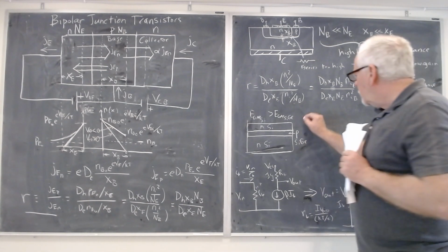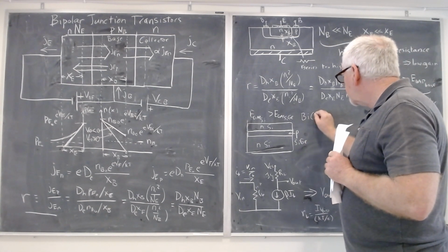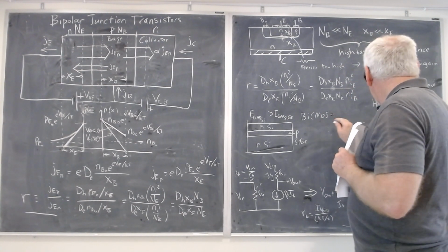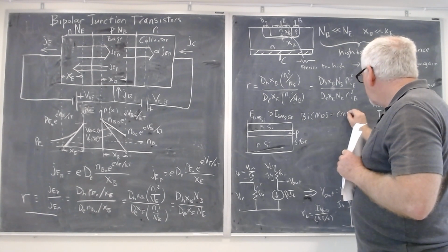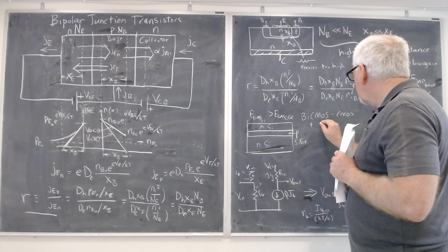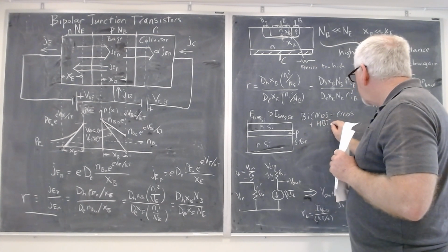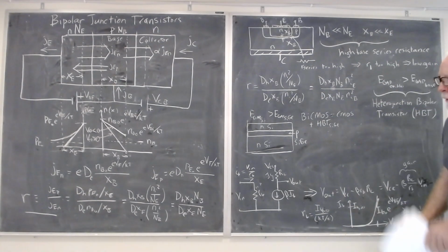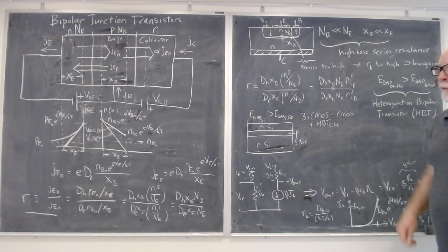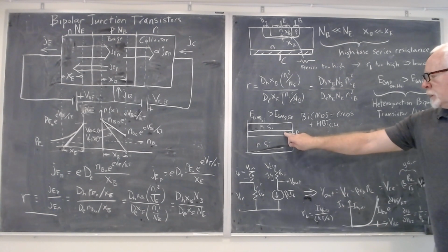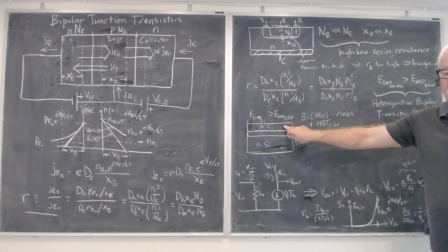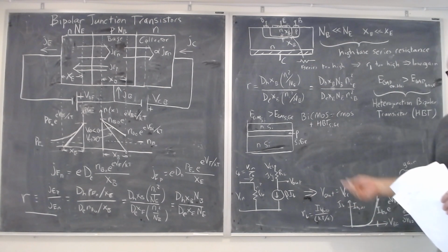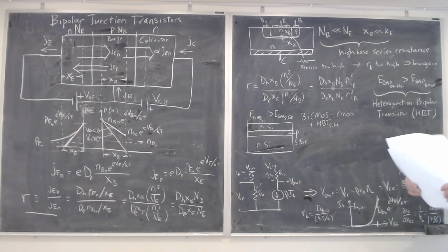And so what's called BiCMOS is equal to CMOS plus HBT based on silicon germanium. And it can be fabricated in the same way for that. You can also do this by fabricating group 3-5 materials. Like this could be gallium arsenide, and this could be aluminum gallium arsenide, or various other ways. And anyone who is especially interested in this, it's called band gap engineering. You can talk to me offline.